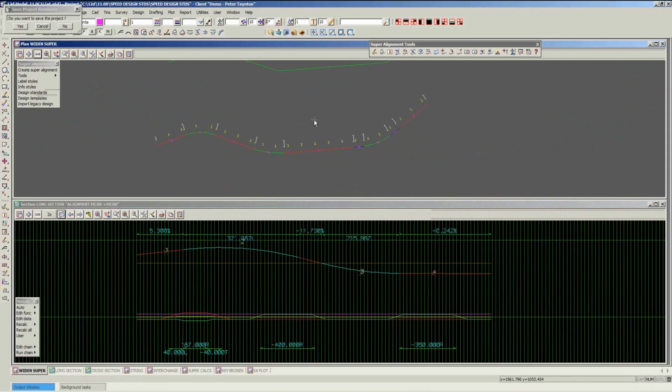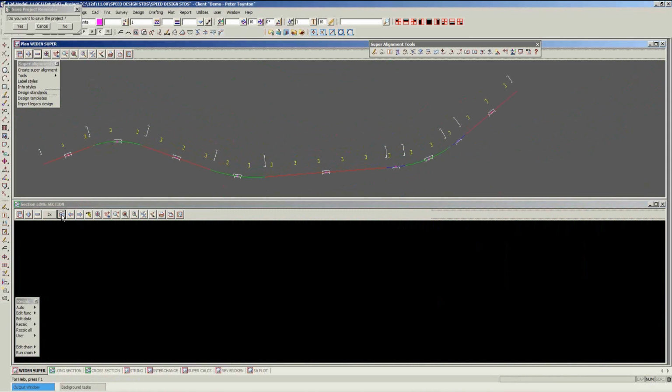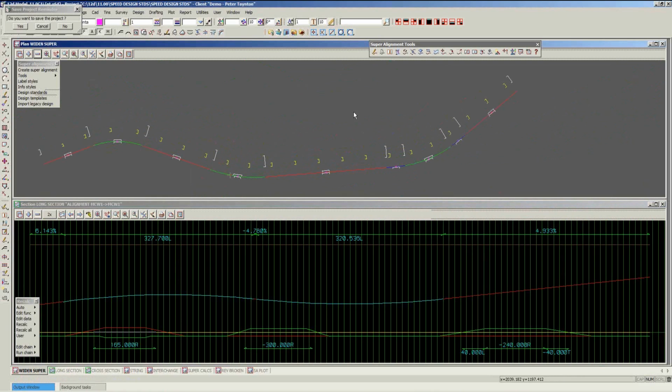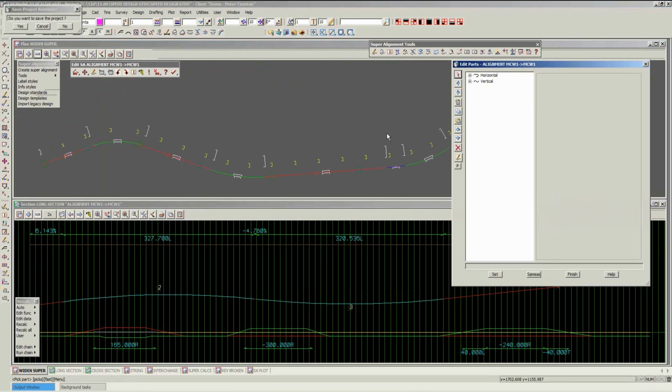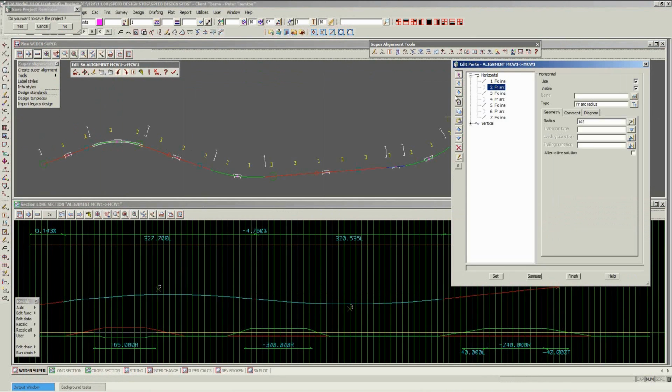So if we look at our design that we've already produced before, this one's an element design. If I profile that, you see it's already got a design speed table attached to it. And again, in this situation you are in the element design mode, so it's not automatically putting down radii for you. The design has done this. So we put a combination of fixed straights and free arcs. The only connection we have back to the design speed is through this little corridor here.